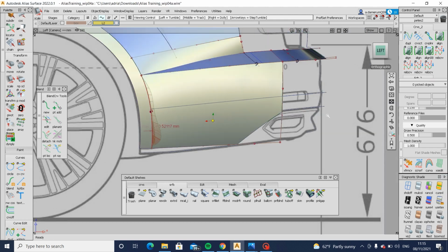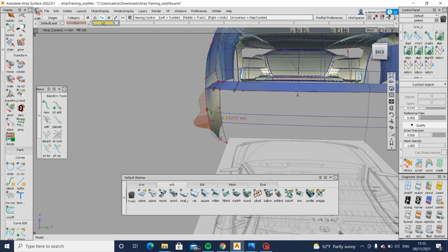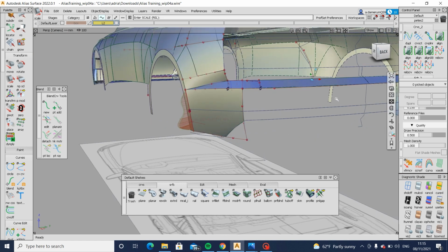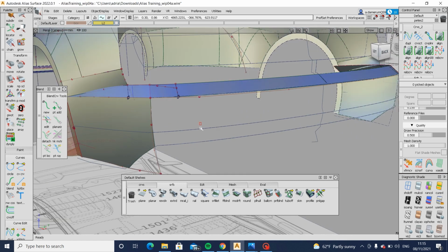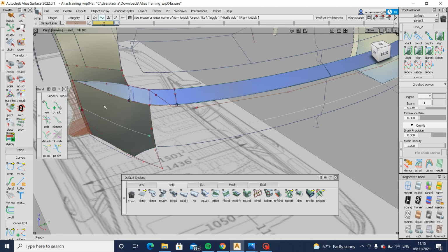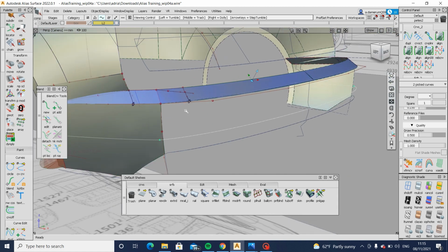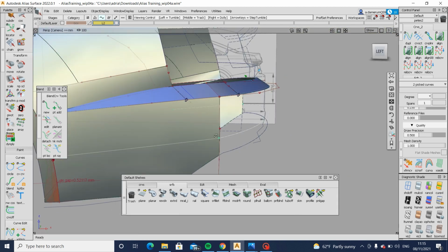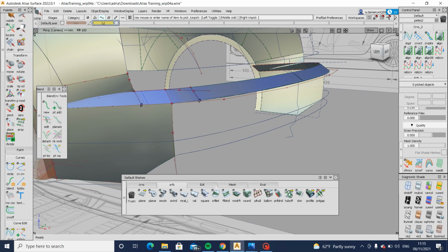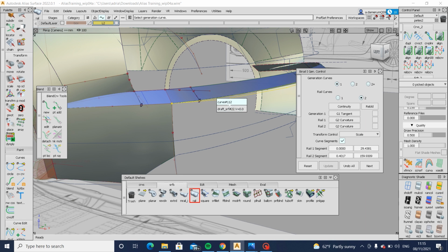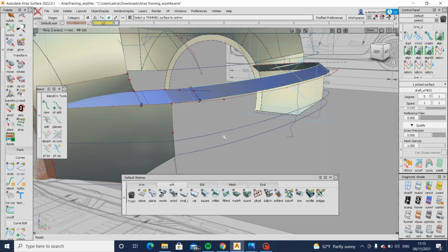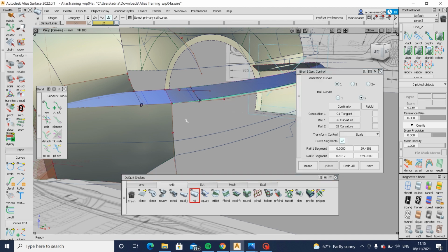Yep. Let's keep going. Let's build this big surface in now as well. And it just looks like there's a little light catcher that flows all the way around. So yeah, let's just build this big surface in first, and then we'll build that little light catcher in here then, because we've got this edge already, I would usually do a rail tool or a draft again. So untrim this edge. Build a rail off of that.